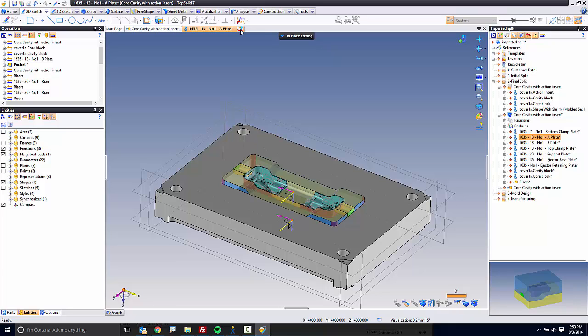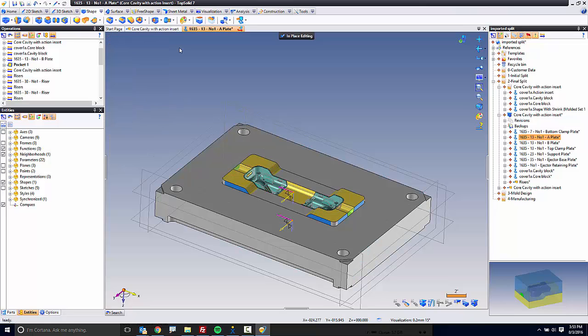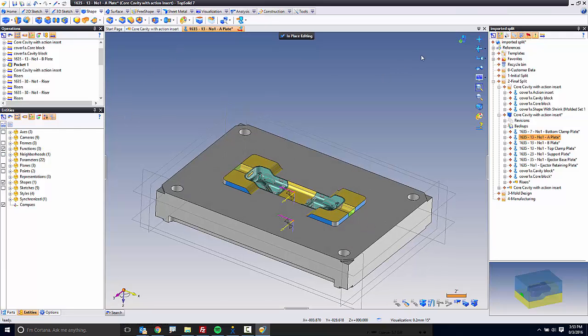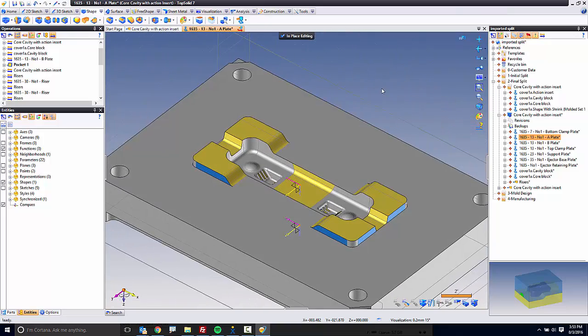The very first thing that I want to do now is this. I want to go shape, unite. So I'll go to my Boolean shape, and I want to unite to it this block, and I'll green check mark it. That's it. The union is done. I can even go to my neighborhoods here and turn it off, and if I turn off the rest of the assembly context, you can see that that is now in solid in my A plate.